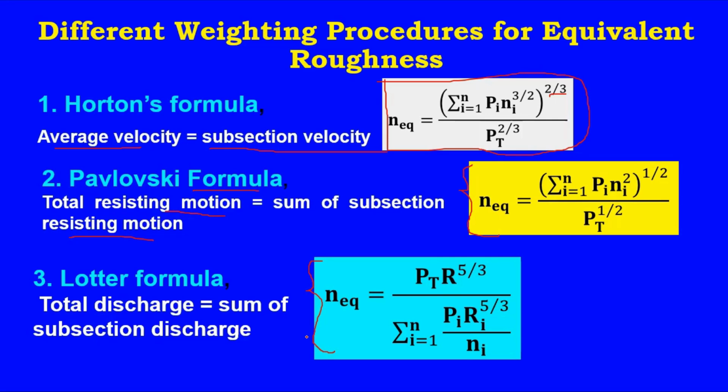So having this in mind, once you use either the whole section method or the partition method, once you compute the total peak discharge going through the compound channel, you will adopt the maximum discharge going through the compound section.